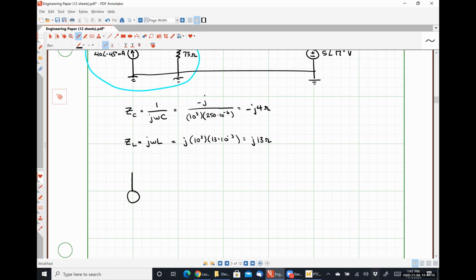When I have a current source IS in parallel with a generic impedance ZS, like so, I can convert that to an electrically equivalent practical voltage source, where the impedance ZS stays the same and my new voltage source is simply IS times ZS.